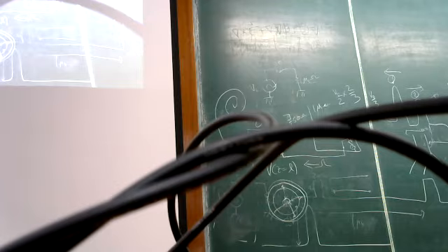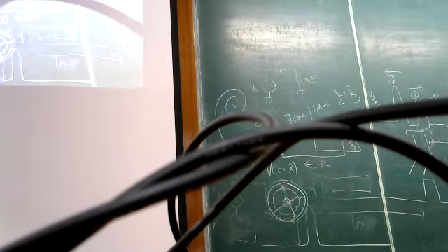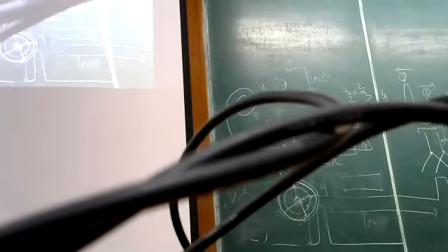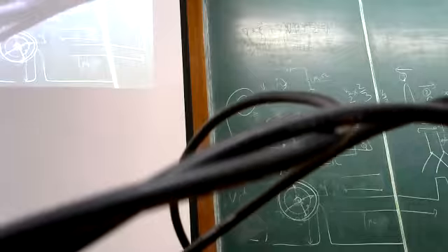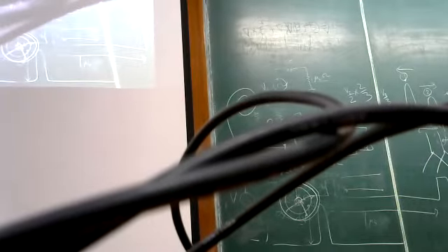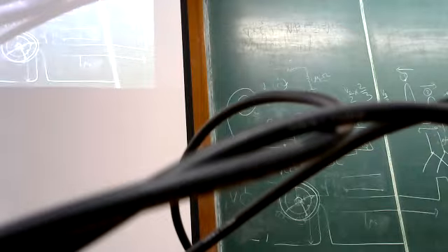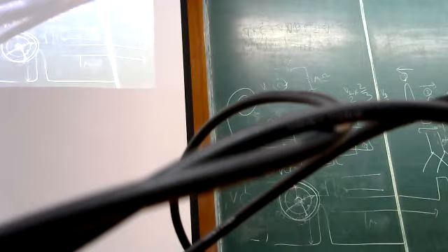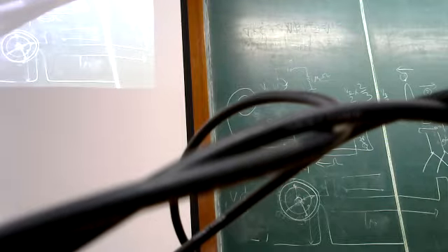A catch is the connector at the end. Okay, and this sort of comes under the entire category of transitions in microwave networks. So remember, in order to create this very long cable, I used a section of a cable. So this coaxial cable by itself is a nice transmission line. You don't expect any reflections to happen while the signal is propagating through the cable. But here, you can have reflections, and in fact, you will have reflection. The reason is this small piece of connector is a small section of transmission line, but made with different dimensions.